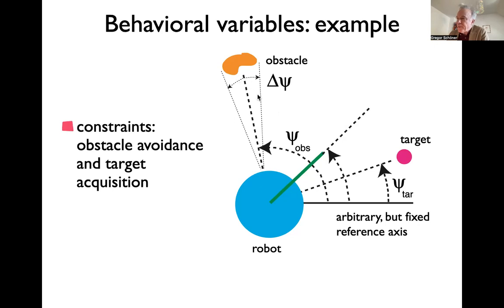The obstacle avoidance can be expressed similarly. In obstacle avoidance, you have a certain angle, called psi obs here, under which you see the obstacle relative to that world axis. Typically you might think of the obstacle being a whole range of angles, because the obstacle might be extended in angle, and you may want to avoid any angle within that direction. So it's like the closest you could be right here on the side of that, and on the other side. And we'll later think about how much of a safety margin you might need to include in your steering. And there will be issues like you don't want to avoid an obstacle when it's very far, so distance dependence will come in. But in terms of the information, that is what obstacle avoidance imposes as a constraint. The heading direction expresses that well. So these are values or ranges of values that determine the behavior.